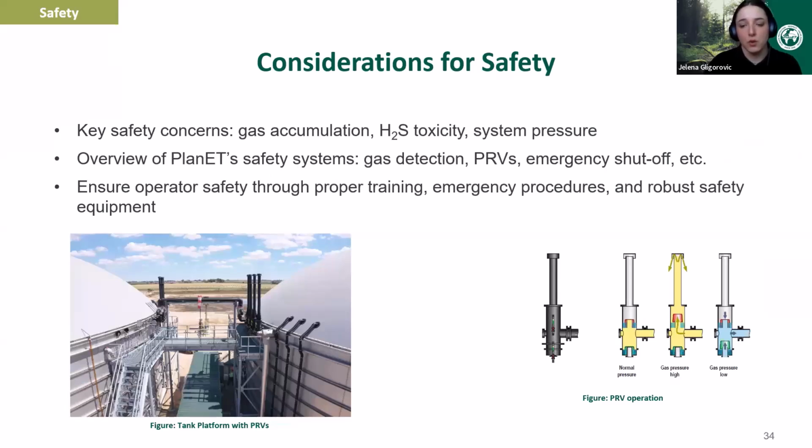So making sure that you are designing for safe biogas storage with pressure relief valves, which I'm showing on the screen here, and flaring systems to manage excess gas. Having adequate ventilation in enclosed spaces to prevent the buildup of gases, having gas monitoring systems for methane, H2S, CO2, and incorporating alarms and automated shutdown protocols.